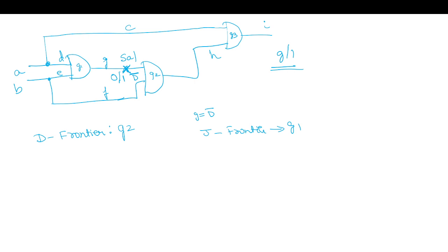Now to propagate this fault, this has to be 1, and a non-controlling value for this also. So now D bar will advance here and D bar can advance here. So we have propagated the fault effect using the D frontier through G2 and then next followed by G3.